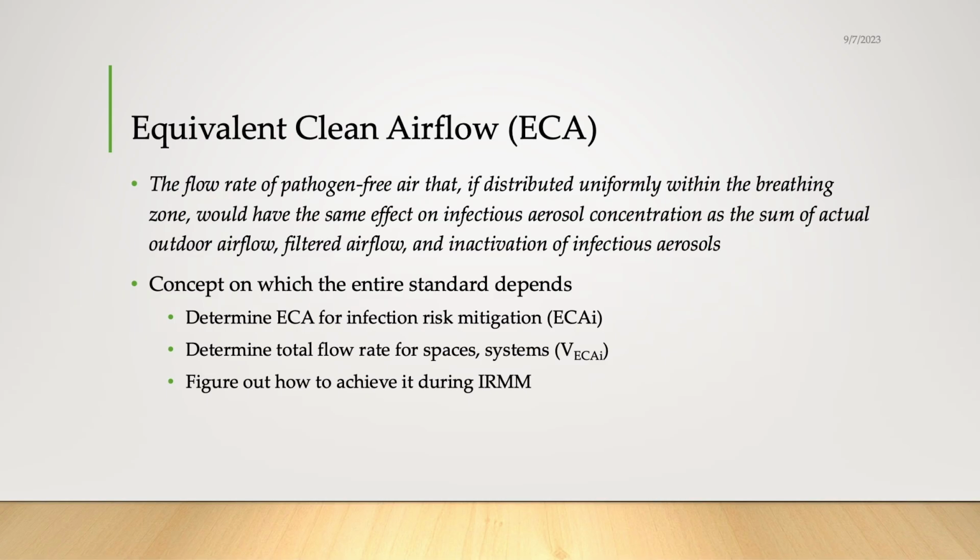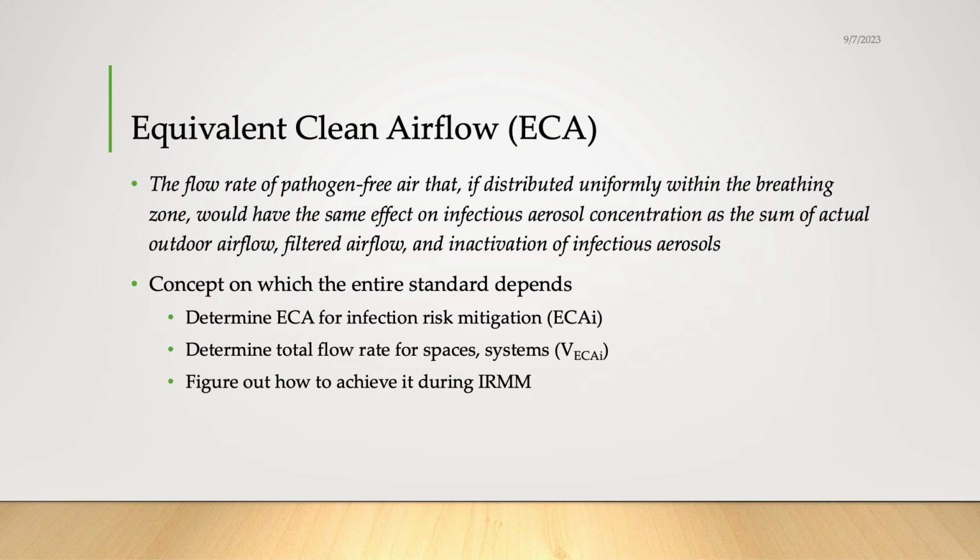And now to the really interesting technical concept here, equivalent clean airflow. And the first thing is to just remember, when we say equivalent clean airflow, we're not talking about outdoor air. If that's all you remember, that it doesn't have to be outdoor air, that's a good start. The idea is that there is a quantity or a flow rate of air that's not contaminated that we could deliver to a space that would have the same effect as whatever we're doing in it.